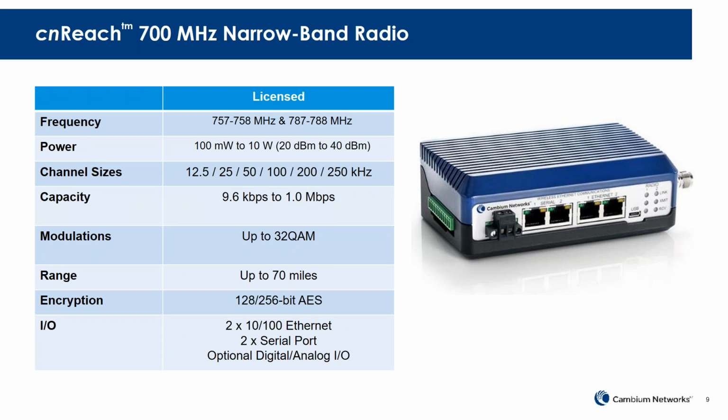the 700 megahertz spectrum. The nice thing about this product in 700 megahertz is that it is 10 watts of transmit power, so it's the highest power product available in this spectrum, and it's also in a 250 kilohertz channel, so you can get real usable throughput.